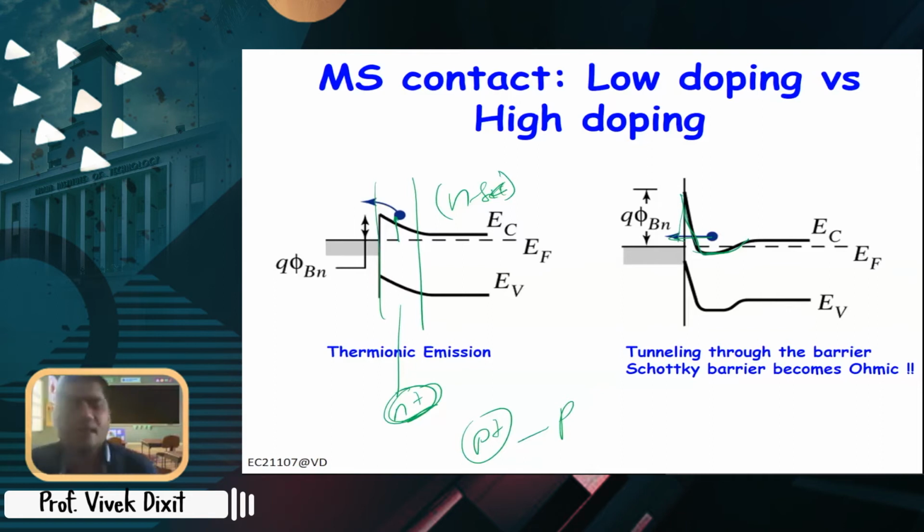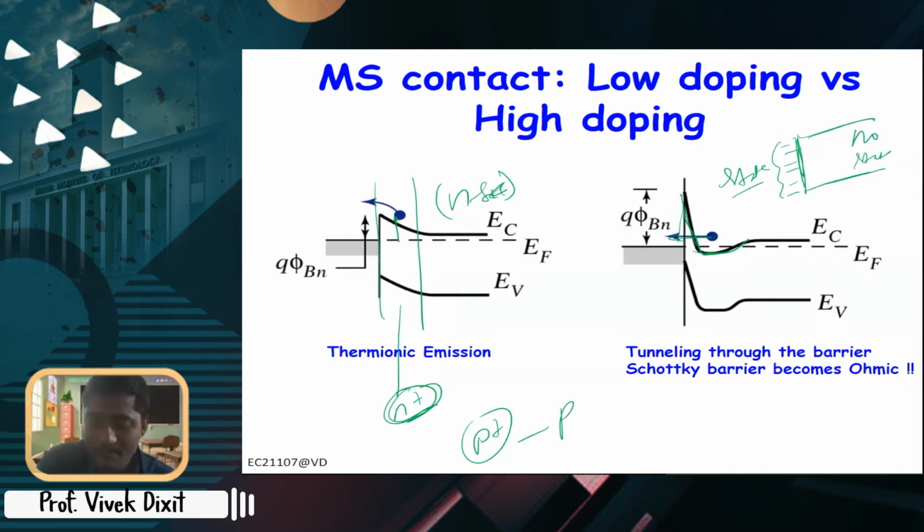Now in real metal semiconductor junctions, there are other factors also. So it is not that straightforward. What happens? You have this piece of semiconductor. Now we are truncating it here. That means there will be dangling bonds, right? And these dangling bonds will create states. Inside the bulk semiconductor there are no states here, but at the surface there are states here. So these states will be filled. So there will be some kind of bending there, right?